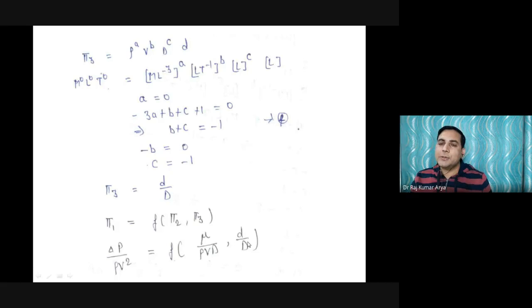Now if you want to scale up this orifice, you have to consider these 3 dimensionless numbers only. These should remain the same from model to prototype. Is this fine till here? This way you get which dimensionless numbers are involved in my problem or in my question.